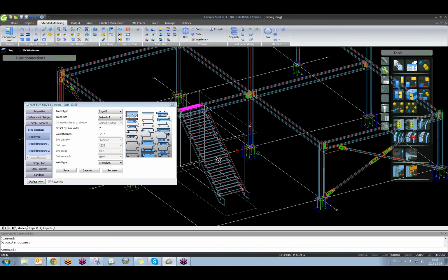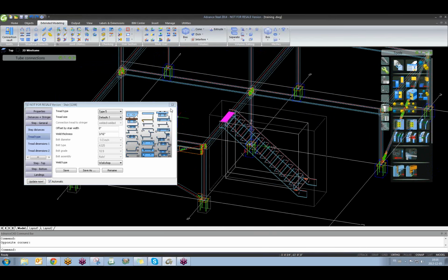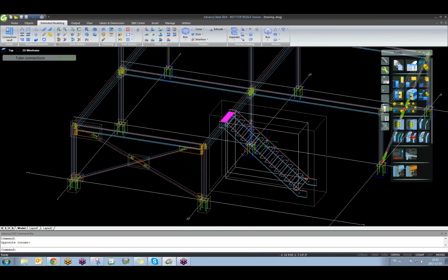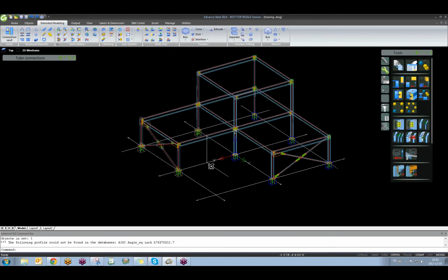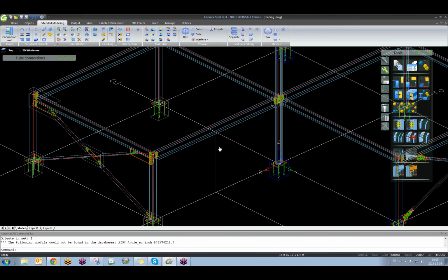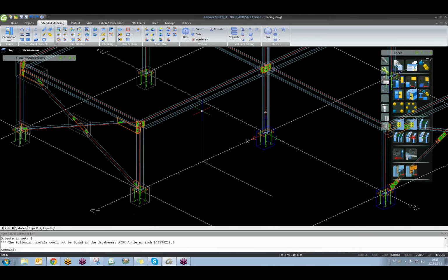Yeah, Hamza, if you could just start over again and step through those commands to get the stair itself in there, before you start to manipulate it, that would be helpful to me. Okay. Just go through the series of commands to get there. I'm going to delete that. The first thing you need to do is draw construction lines. You will have the values on your plans. For my training, I just put some values, but in here, if you pick straight stair,